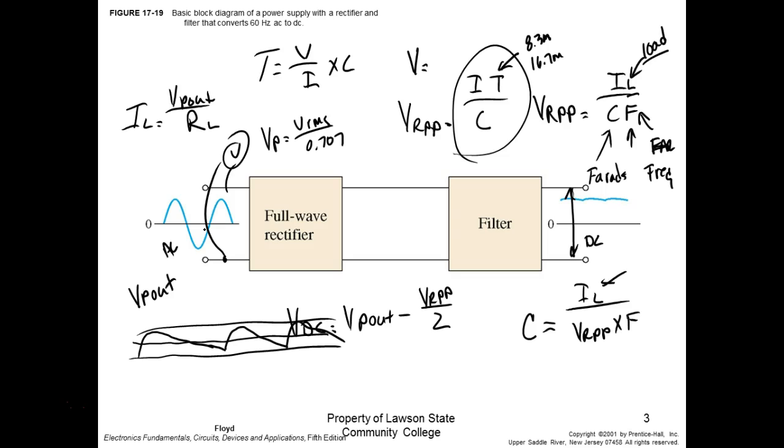You could have a faulty transformer. You could have a shorted winding in your transformer. Y'all looked at that magnetic wire? Y'all seen magnetic wire? The orange stuff. The insulation is extremely thin because it's trying to get really good coupling between the wires, right? You understand that? Transformers vibrate. Which means that if they don't tie those things down really, really well, then those wires vibrating together might wear that insulation out and they'll short.